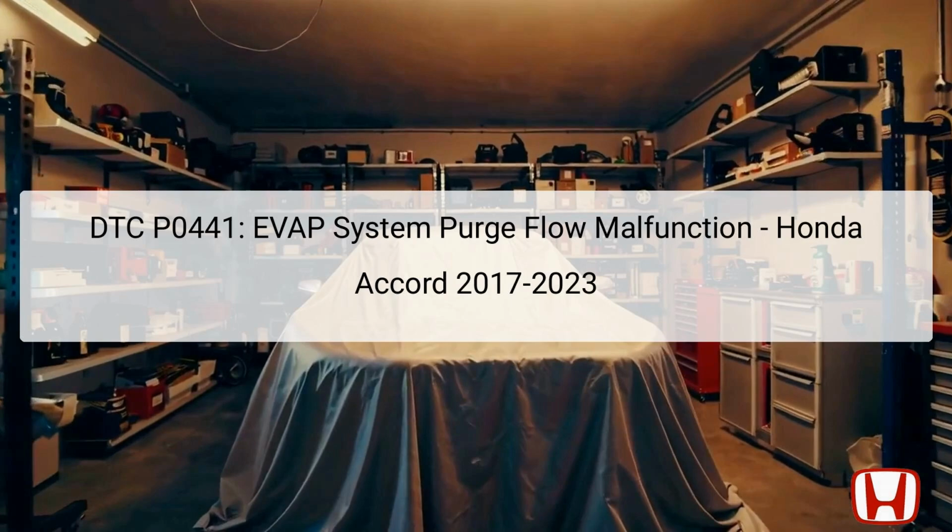The Diagnostic Trouble Code, DTC P0441, indicates an issue with the Evaporative Emissions Control System, specifically indicating a malfunction in the system's purge flow. This code commonly appears when the Electronic Control Unit, ECU, detects that the purging of fuel vapors from the charcoal canister to the engine is not occurring as expected.